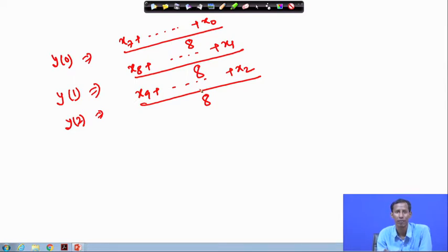And the newer samples will be collected in the averaging circuit for doing this averaging, where the samples are coming serially to the circuit, and the values of the incoming samples are changing dynamically. So, this is the corresponding circuit, and this is the concept of a running average circuit.